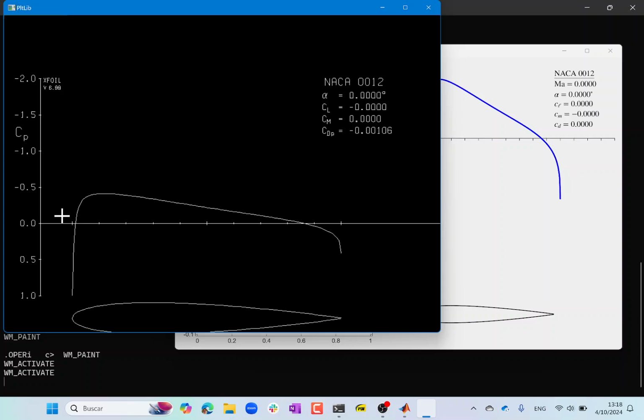What do you get? We get the half of rho u squared is equal to how many times half of rho u infinity squared? Yeah, 3/2. So it's equal to 1.5 times this much, which means the velocity is equal to how many times the u infinity squared?